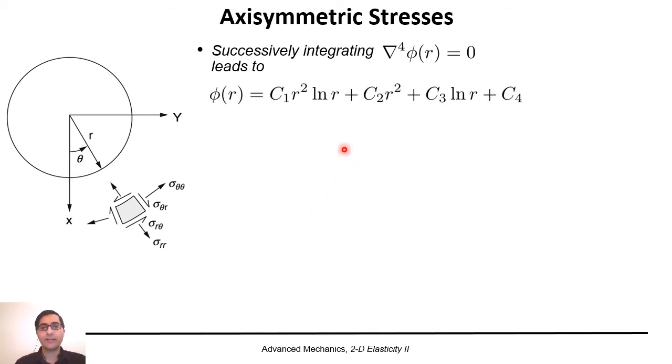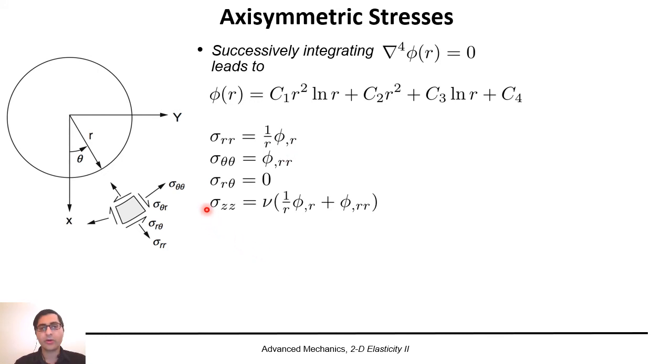Okay, now having the Airy stress function, we already know the relation between the stress tensor in cylindrical coordinates and the Airy stress function. So it's a matter of just simple substitution.